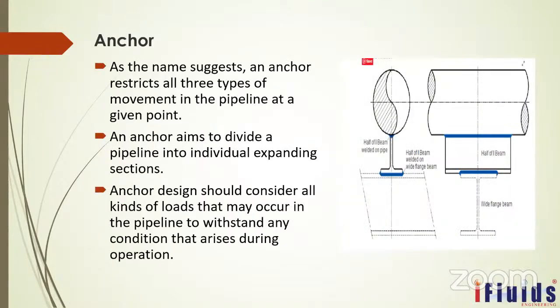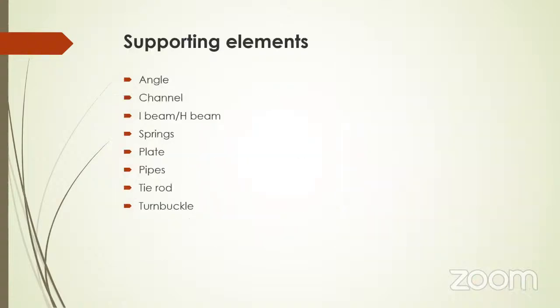So first we have seen the shoe support, saddle support, U-clamp, plain clamp. After that, anchor support and guide support. These are all the types of support, I mean the arrangement structure. Now, what are all the elements we are using in pipe support? Angle is a ready-made section. It is available. For guide supports and similar, we will go for the angle. And then channel, where heavy load pipes are there. The next size is channel.